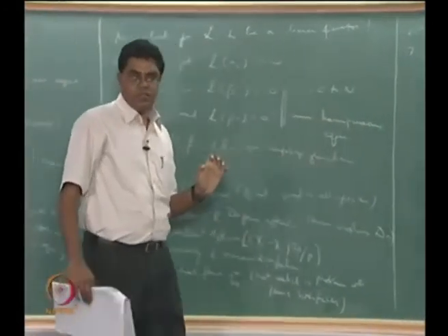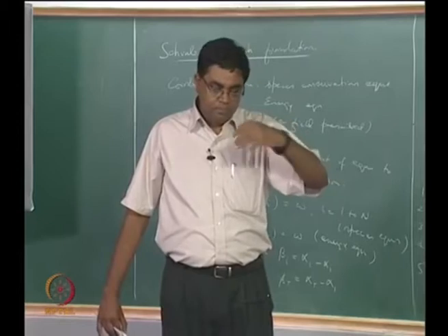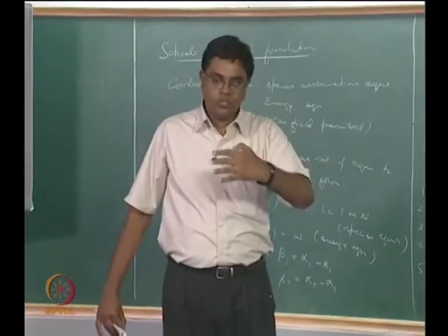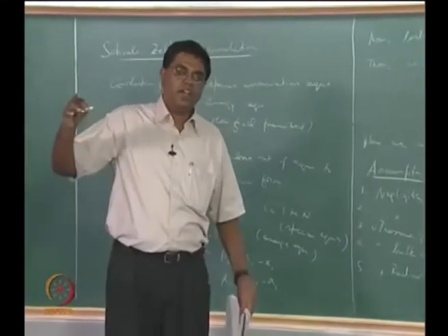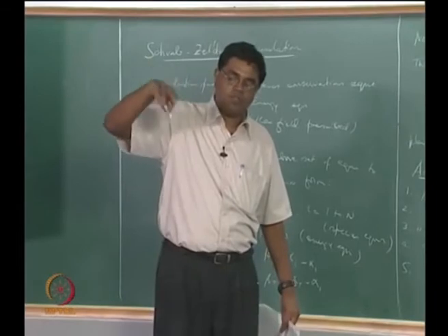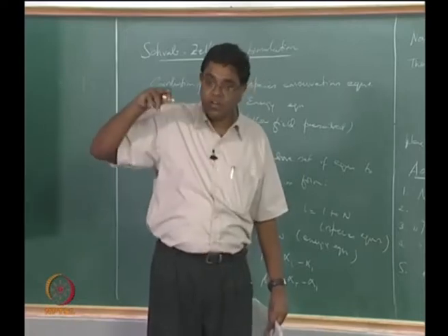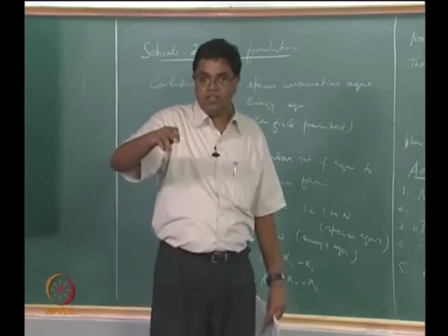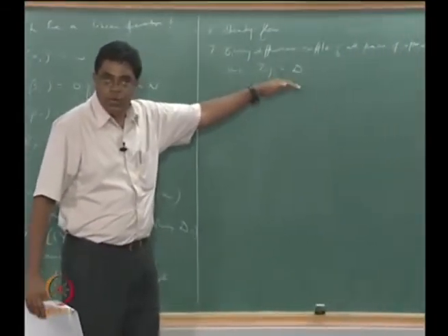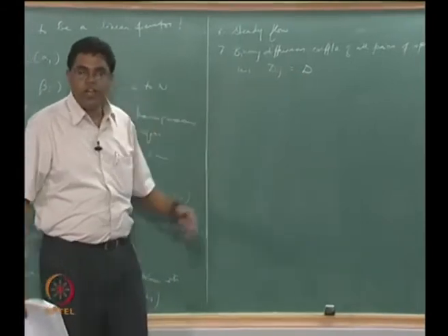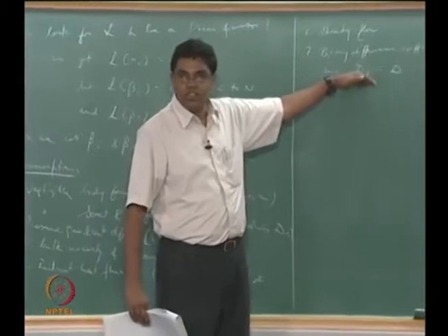But we are saying here that all of them are going to be equal for all pairs of species, and this is very important for you to be able to plug your multi-component diffusion equation into a Fick's law and then plug that into the species conservation equation. Otherwise what happens is you now have grad Xi equal to some coefficient times Vi minus Vj, and you could derive Fick's law only for a binary mixture where again DAB is equal to DBA, and since only two of them are there and they are equal, it's just as good as this assumption, and then you could have obtained Fick's law. That's what we did before, but here we have to get past that for a truly multi-component mixture of more than two species. Therefore this assumption is necessitated.